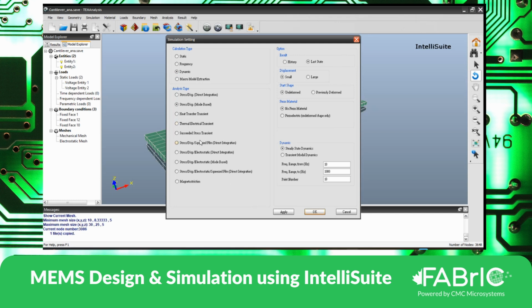Okay, so going back again to stress displacement electrostatic. Here we get these options of fixed capacitance option, updated capacitance option, or we want to do a stress displacement squeezed film, because here we can also define the medium around the device.